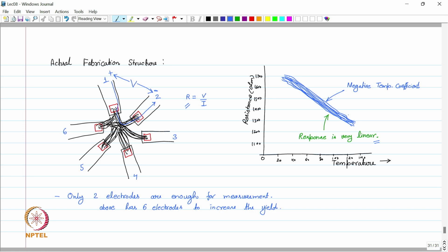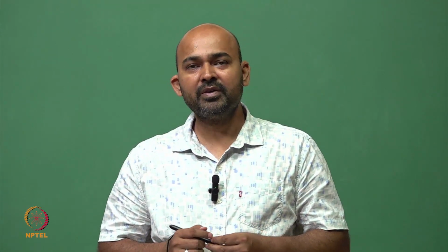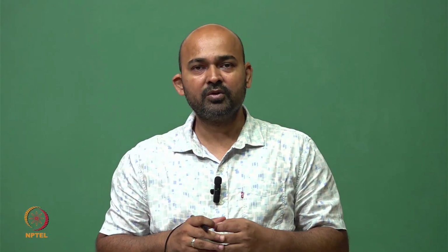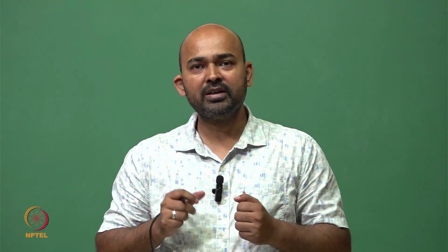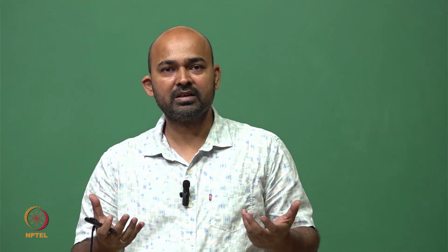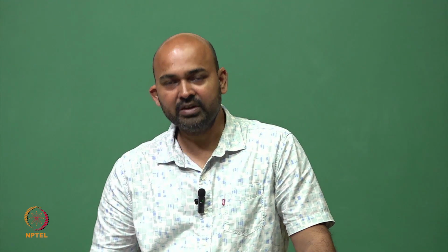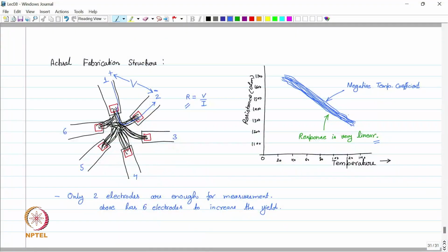So this is how we can make a thermal sensor using carbon nanotubes, where we have seen how to join these CNTs together. We saw that when we grow the CNT, it's very difficult to make a second connection on top of the CNT. So what we do is grow two CNTs together and join them on the top using this condensed liquid, or acetone. We put the acetone so that they mix up or juggle up with each other. Then we evaporate this acetone so that they remain in contact, and when we make a contact between two CNTs on the bottom, they have different pads, so we can measure the resistance between these two pads electrically, and we see the response. The resistance is changing with temperature. So this is how we can make a temperature sensor using CNTs.